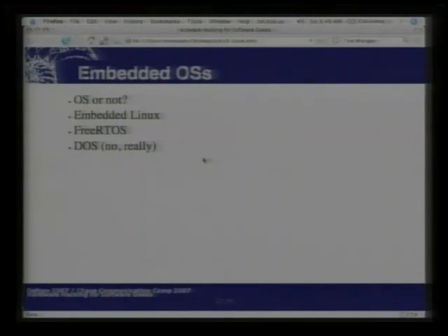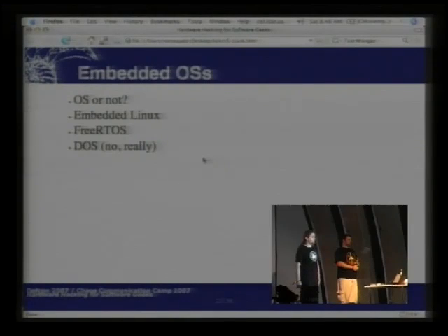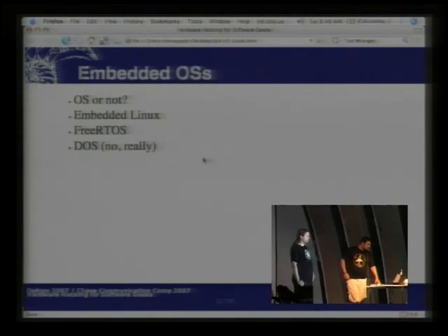And what that will do is it'll preemptively schedule. So it'll stop whatever it's working on to meet specific deadlines that are critical. So it schedules tasks based on priorities, distance from deadlines, and things of that nature. It all depends on what your needs are for that. You can also use embedded Linux. Routers will typically use embedded Linux or VxWorks.